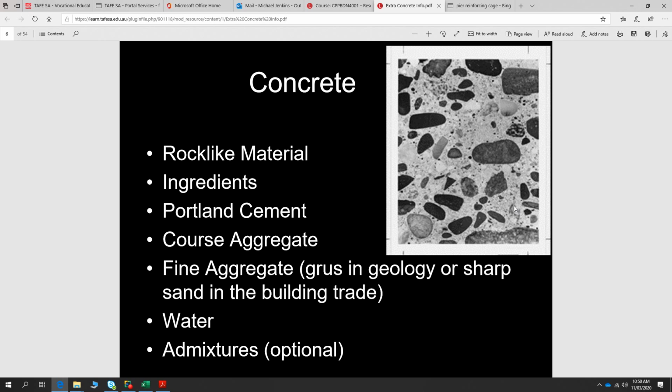So typically you want to have that slag or that fly ash in there to slow down the reaction, make things easier for the concreters, and enable your concrete to travel further. It also makes it more workable and environmentally friendly, because there's less electricity that goes into producing that cement powder.